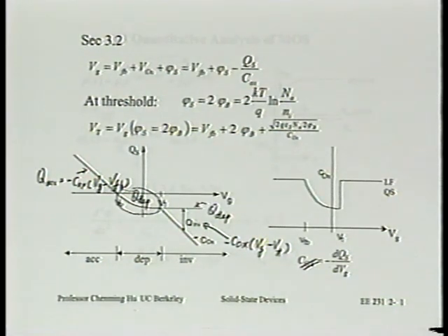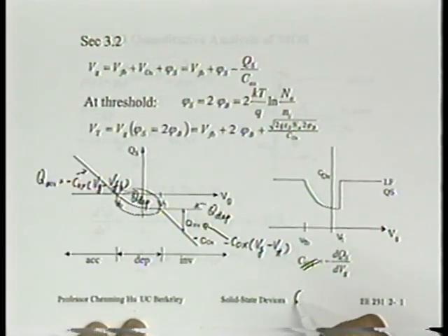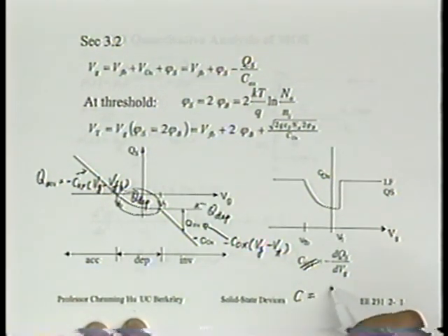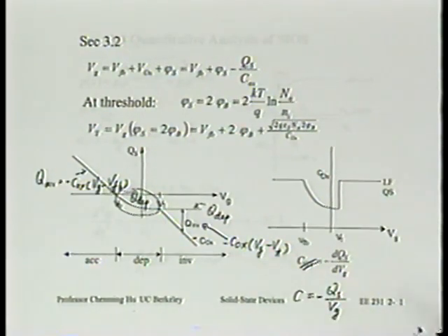In fact, even with PN junctions, we usually talk about small signal capacitance. So here, the capacitance we're dealing with is small signal capacitance. If we talk about large signal capacitance, it would be Qs over Vg, right? You already know what the minus is about. It's because we're taking the voltage and charge from opposite plates of the capacitor.